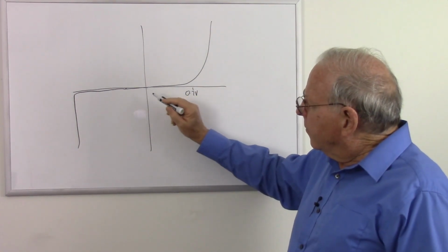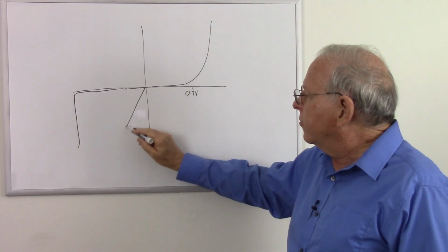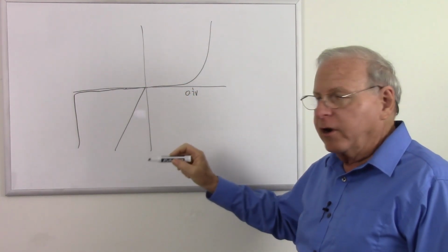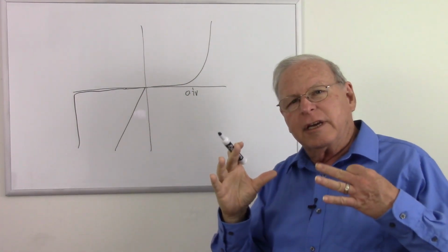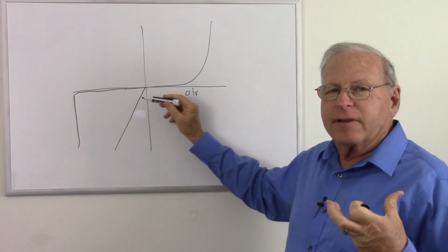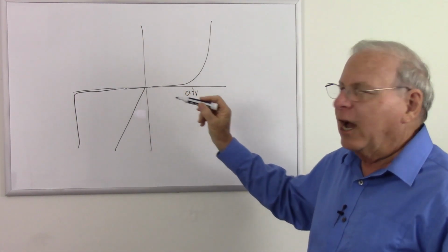The tunnel diode, when it's reverse biased, it looks pretty much like a resistor. So there is the reverse bias curve. As I increase my voltage, I increase my current, and of course this is going down because I'm just showing that when it's reverse biased, I have negative current. What does negative current mean? It just means the current's going the opposite direction.